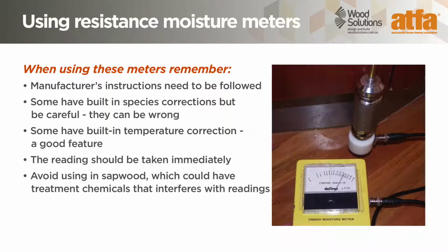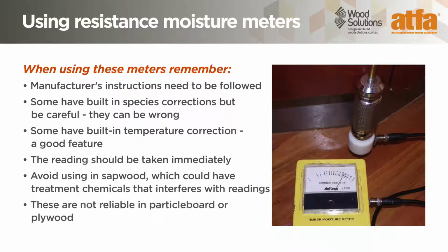Avoid using in sapwood. It's often the lighter coloured wood in a board which could have treatment chemicals that can interfere with a reading. And these meters are not reliable in particle board or plywood or bamboo.